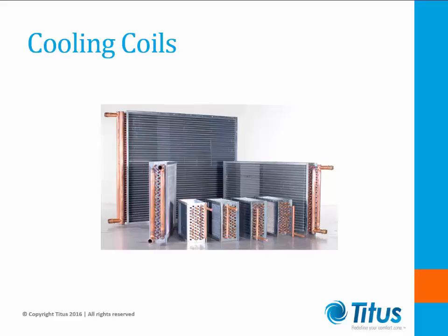Filter sections are provided upstream of cooling coils. In many installations, the filter section is utilized as the intake section of the air handling unit, foregoing the mixing box section. In the upcoming slides, we'll look at the V-bank filter configurations and the effects they have based on their placement.